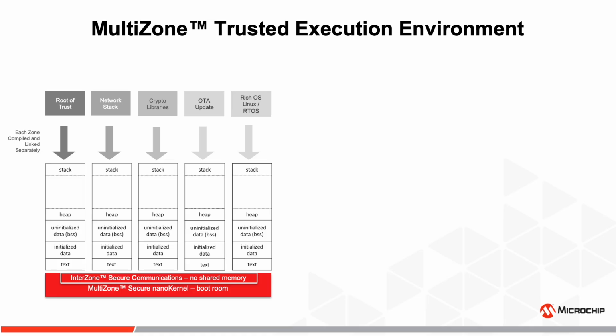And of course, then you'll have any kind of combination of rich operating system or real-time. And there are only 5 here because that's a slide, but there can be more there. And so just to give an idea what's possible with these 5, if properly orchestrated, it's multiple, equally secure zones, so there's no concept of a secure world and non-secure world. Either you get separation or you don't, so they are all separated, they are all secure, they all run in user mode. And anything can be mapped to those zones: RAM, ROM, I/O, and their handlers.